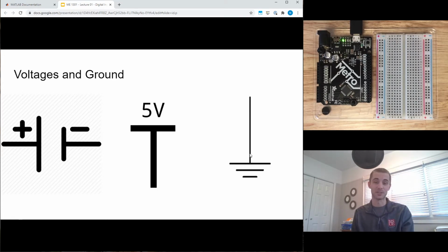If you're connecting directly from 5 volts to ground, you are making a mistake, and you are probably causing the chip in your computer that controls USB to draw too much current, and it'll probably turn off your USB devices.